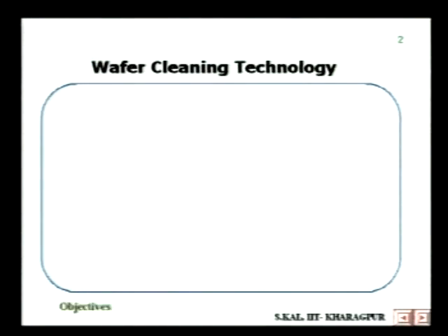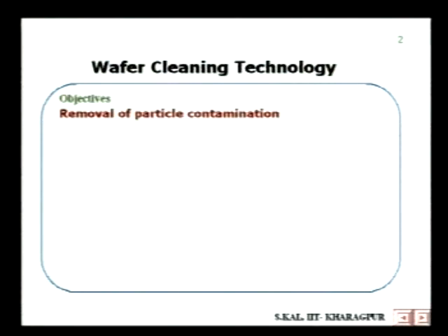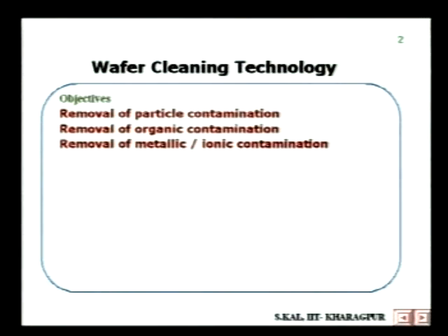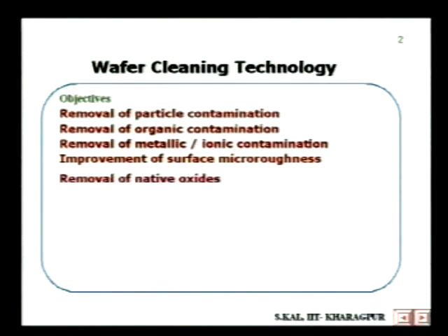Now, let me discuss the objectives. The primary objectives of wafer cleaning technology are removal of particle contamination, removal of organic contamination, removal of metallic or ionic contamination, improvement of surface micro roughness, and removal of native oxides.